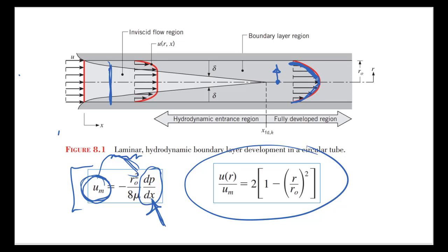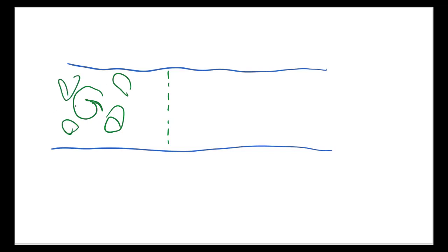But of course, remember that if we are in a situation where we have a turbulent boundary layer, and we have our pipe, what that essentially means is that at any given cross section the fluid is swirling back and forth. It's all these vortices, and you're getting a lot of mixing. So for a large extent of the cross section of the pipe, you're getting a fairly constant velocity. It looks very flat in the front of it.